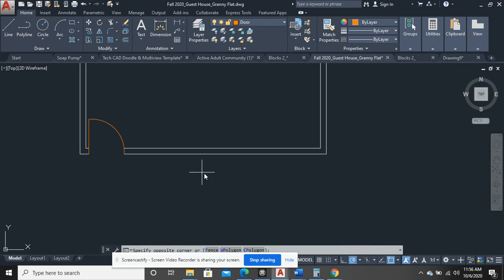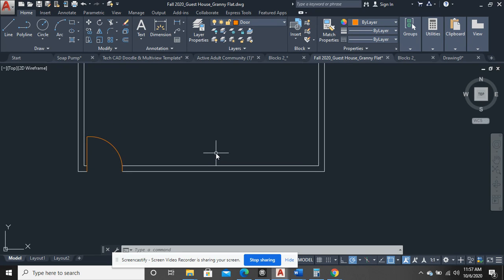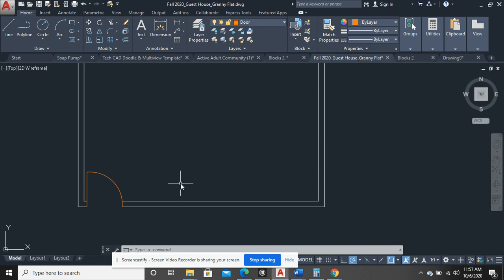If I had put my door in the center of the room or the center of the mini house or whatever it is, there's probably not a wrong or a right answer because the door in either case is going to use up area on a flat wall. If that's the case, then my question becomes, where are you going? What's your pathway? Is this your primary pathway? This is what we would call a traffic pattern. So in that case, you want to make your door swing away from the traffic pattern.